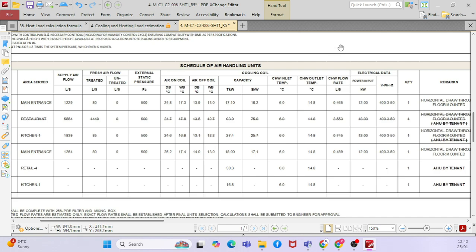Okay, sir. Multiply by 24, it's just a value. Divide by delta T. So what is delta T? This temperature difference, right? It should be in Fahrenheit. So convert this one to Fahrenheit, then convert this also to Fahrenheit, then see the temperature difference, right? So you will find out the temperature difference. So GPM evaporator is nothing but TR from here multiplied by 24 divided by delta T from here. So you can calculate GPM, right?